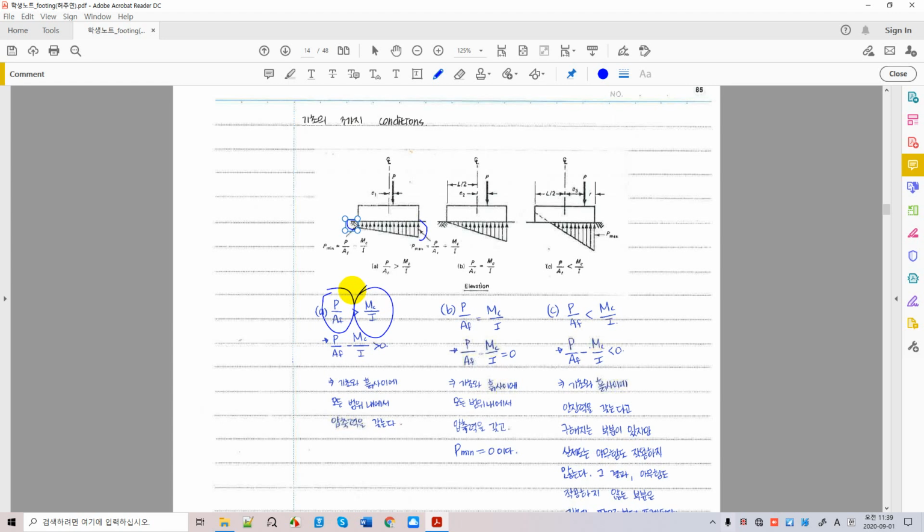The last case is the other way around. The stress caused by the overturning moment is greater than that from the vertical load, so we will experience some tension region, which is very bad for the foundation, because the foundation is going to lift up. It's going to cause a lot of problems for the building sitting on top of these shallow foundations.